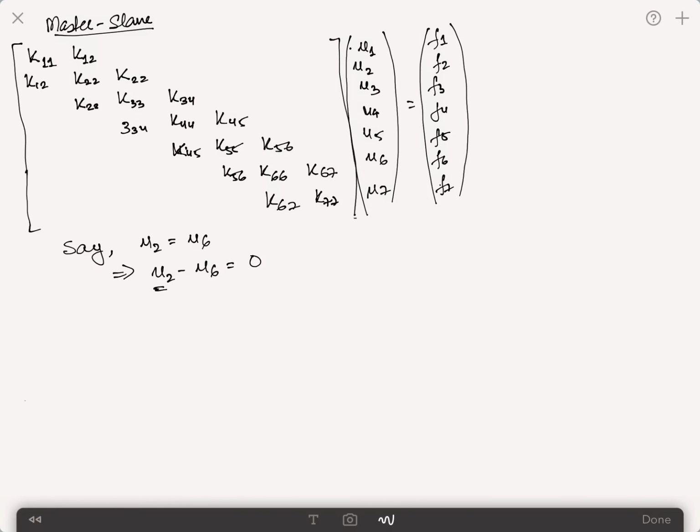So I can also describe this multi-point constraint as a weighting function times stiffness element. So I have that stiffness W, which basically is a K that we are used to. Stiffness element times U2, U6 is equal to no load acting. There's no force at all. So this becomes my equilibrium condition, and this K is very, very high.